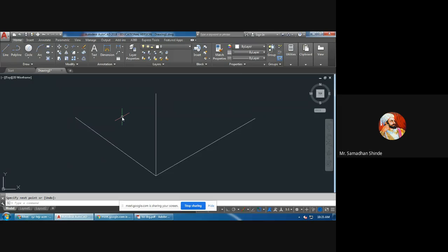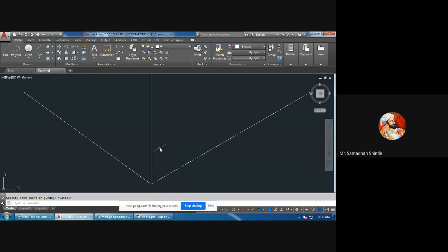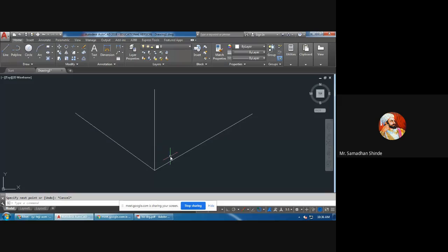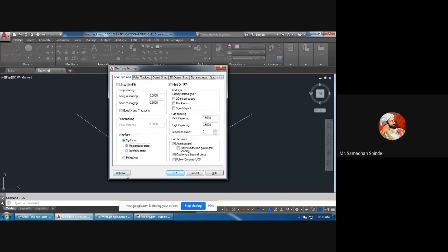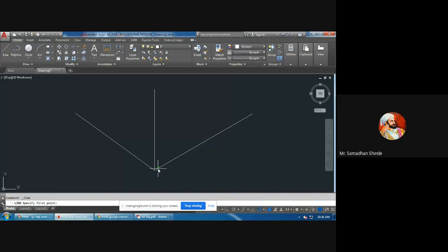In graphics, you may know this. Whenever you observe, only these three lines will be there in the drawing. Which are these lines? They are called isometric lines. Three lines are there: one is vertical, one is 30° going towards the right-hand side, and another one is 30° going towards the left. I will show the angles as well here. Line.